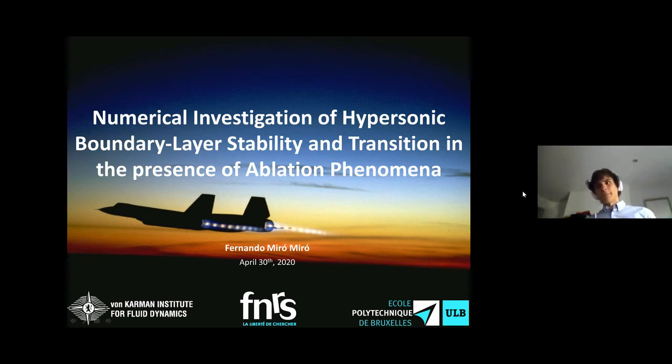It doesn't necessarily reflect what it is. So now that we have all this packaged together, blowing, ablation, chemistry and wall reaction, what would be your take on the possibility of making this kind of analysis with a more comprehensive model, like for instance porous surfaces, where you consider everything at once, and basically you bypass entirely the problem of a boundary condition at the wall, and you estimate everything at once, possibly in a true way.